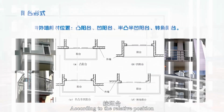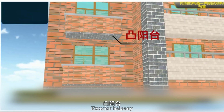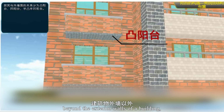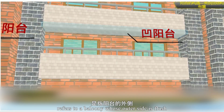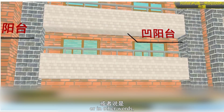According to the relative position between the balcony and the exterior wall, it can be divided into convex balcony, concave balcony, semi-convex and semi-concave balcony, and corner balcony. A convex balcony refers to a balcony that protrudes completely beyond the exterior walls of a building. A concave balcony refers to a balcony whose outer side is flush with the exterior wall of a building, or in other words, the balcony is recessed inside the building's exterior wall.